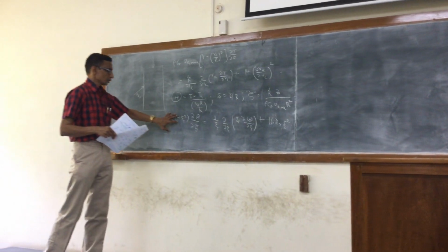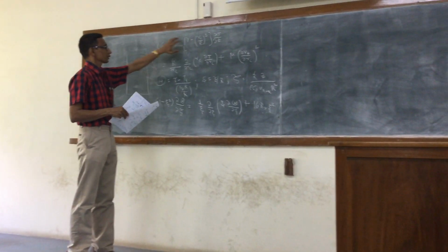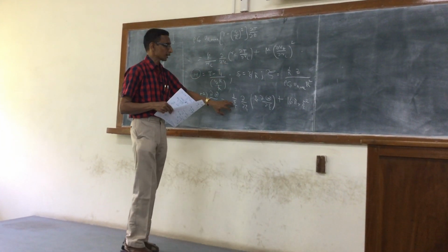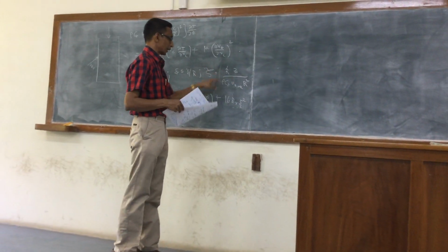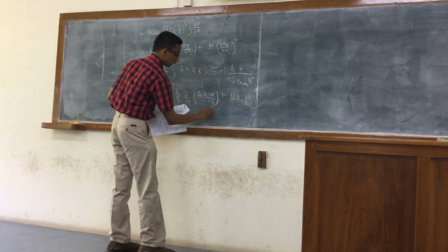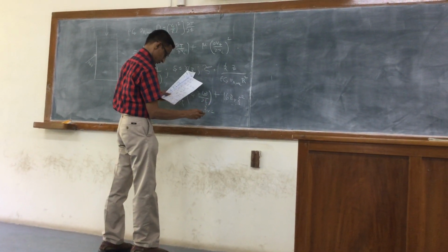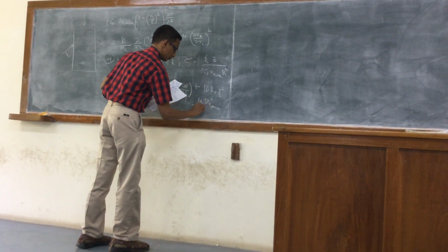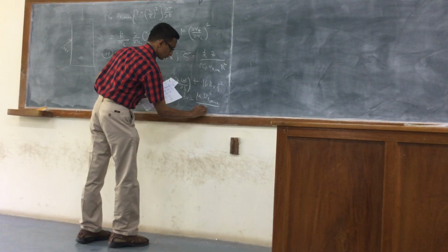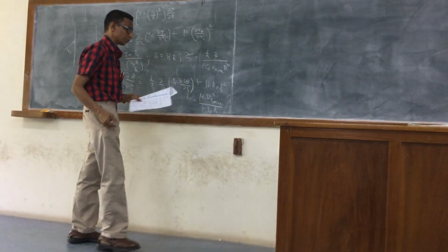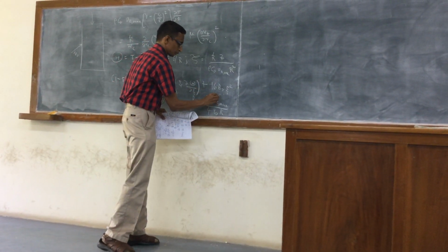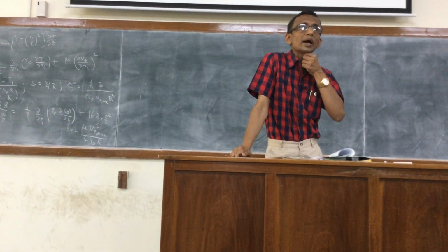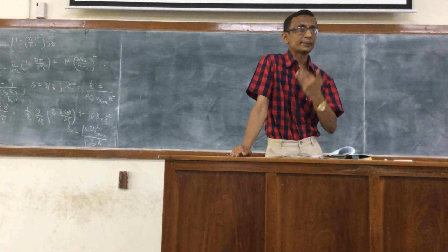This is the left-hand side here. So we are getting 1 minus psi squared comes in here, and then you have, instead of RC, we have psi, and then all of these parameters are contained now in the Brinkman's number, which is given by can be regarded as representing the effect of the viscous dissipation to that of the heating that is externally provided.